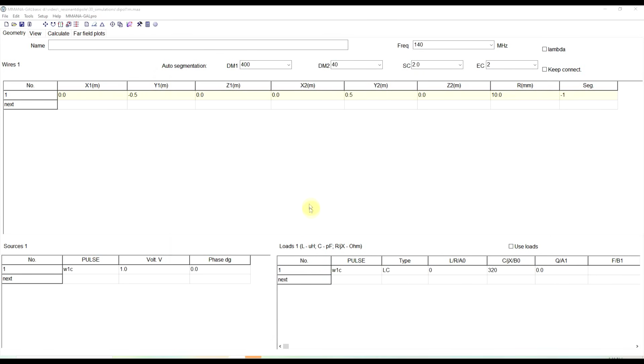Now, theoretical infinitely thin antennas are interesting, but not something you will be building anytime soon. So let's start looking at practical dipole antennas. As before, I will be simulating antennas using the MMANA-GAL software, and for the sake of easy numbers, I will start with a 1 meter long dipole, so it's plus minus 0.5 meters. And based on its length, this structure is a half wavelength at 149.89 MHz. But as already predicted by the theoretical dipole, the resonance frequency will be lower somewhere.